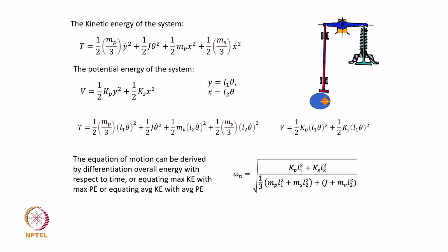Once you get to solve for natural frequency or vibrationary response, how do we make sense out of this outcome, right. So, I would suggest that you use the numerical values which are given in the previous slide to obtain the value of omega n, and then what has been asked or indicated in the example is that you find the value of the spring stiffness Ks, so that this resonance is kept 20% away from the engine idling speed.